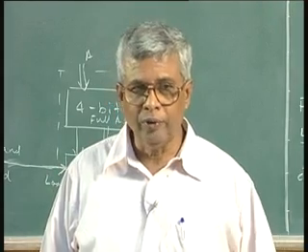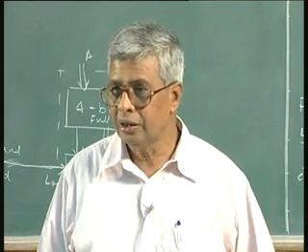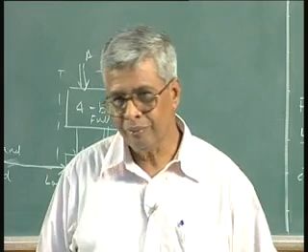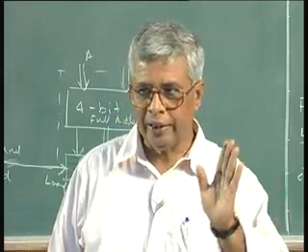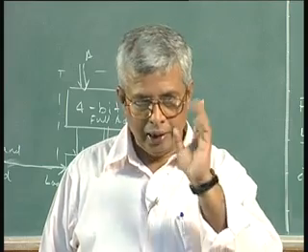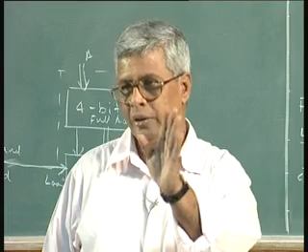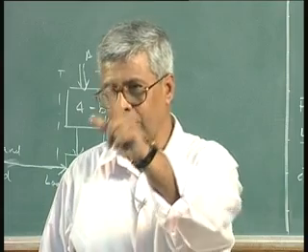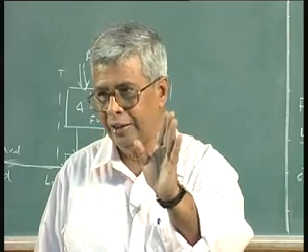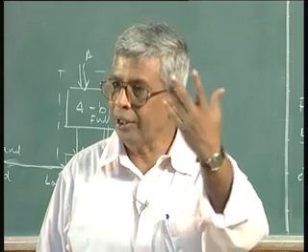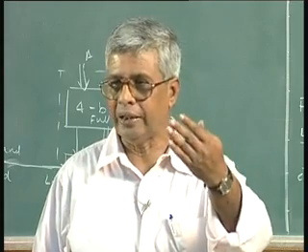I can do it so many ways. I can add the bits, do what? What I can do is to look at one bit at a time and keep shifting it. So I will always look at the LSB, the least significant bit. If it is 1, I will add 1 to the register B and then shift it, because the algorithm must be simple. I can think of so many other ways of doing it, but the simplest way I can think of is,